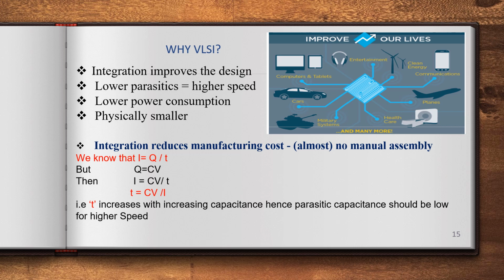Parasitic means there is always a non-zero capacitance between any two conductors. This can be significant at higher frequencies with closely spaced conductors such as wires or PCB traces. Similarly, unwanted capacitances exist between the terminals of a transistor. This is unavoidable and usually unwanted capacitance that exists between the parts of an electronic equipment simply because of their proximity to each other. This is called parasitic capacitance, stray capacitance or self-capacitance.